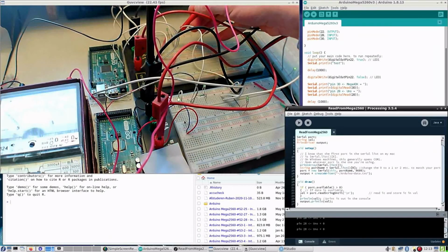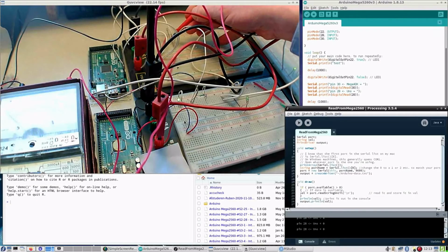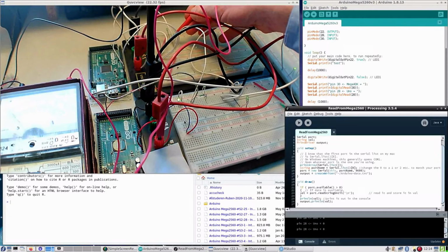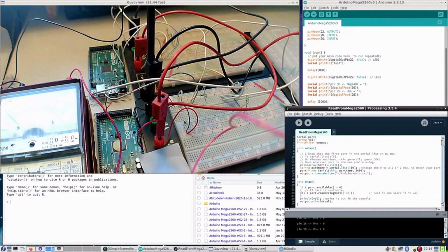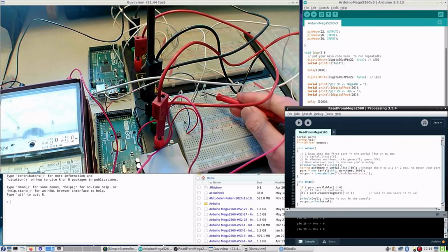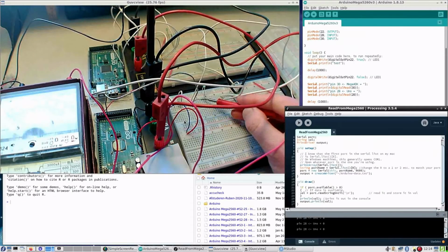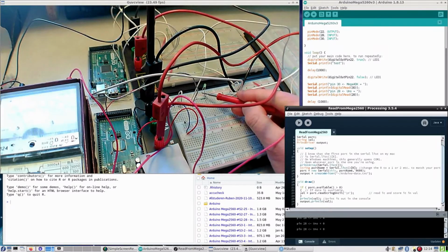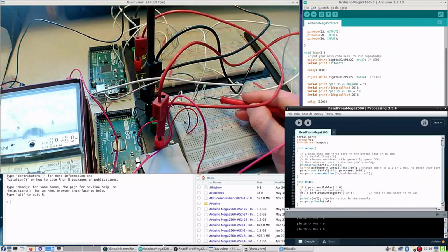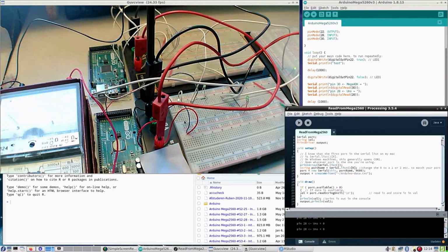Measuring here, you can see that the needle right here is moving, so there's voltage. Measuring here, you can also see the needle is moving, as is with the LED. It's a bright light shining on it, but you can see the movement of the needle. That means that there is no wiring issue.